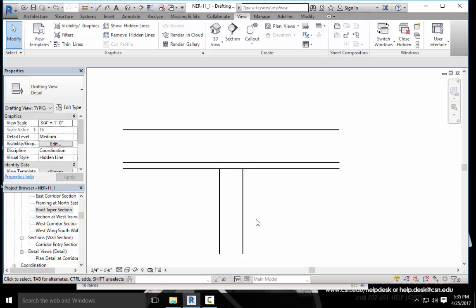Click the Trim Extended Corner button on the Modify tab as shown in figure 11.56. Or type TR. I'm going to type TR. And we're just going to take this and click on the pieces that you want to keep. And we should have something that looks similar to this.